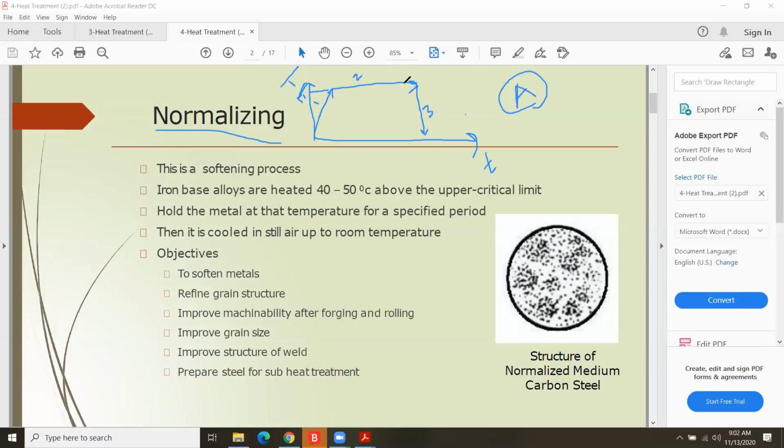This is just a common calculation, right? So if you have 25 millimeter steel, that can be diameter or the thickness, then you have to keep that heated steel for a 1 hour period of time, right? So the holding process, or the soaking process, is finished.